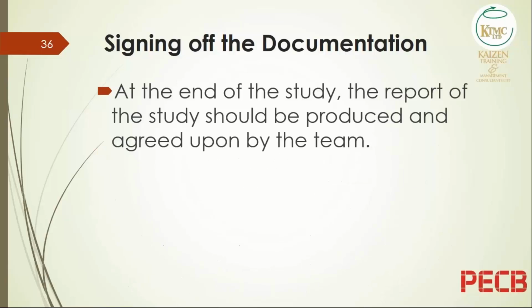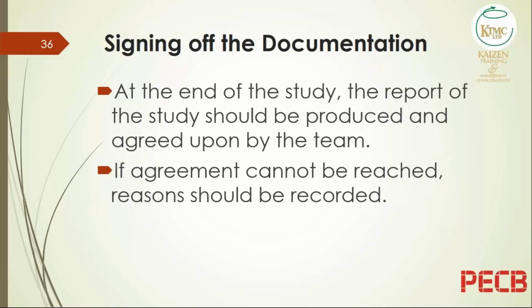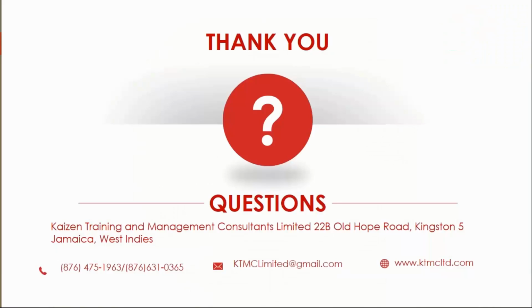The signing off of the document at the end of the study is important. The team leader, the secretary or recorder, and of course, team members; note should be made of all participants. This is a document that can have serious repercussions from a regulatory point of view and for the functioning of the organization. There may be disagreements. If agreement cannot be reached, the reasons should be recorded. So there may be differences of opinion among team members, and this is sometimes the case. That should be recorded as well.